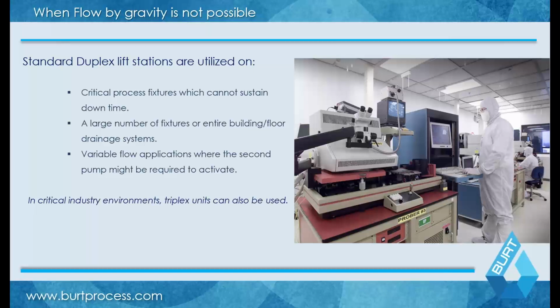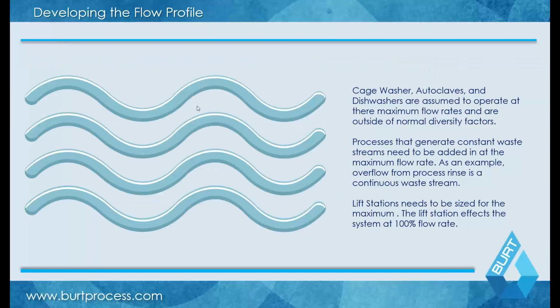That's because you generally want your pH system not in a pit. You have chemicals, you have probes to calibrate, you have control systems. So ideally, you don't want that stuff below ground where you have a confined space entry. You generally want to put some kind of a lift station that allows you to control the flow into your system. It can even act as a quasi-equalization tank to then feed into your pH neutralization system.